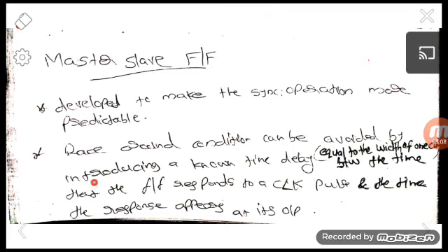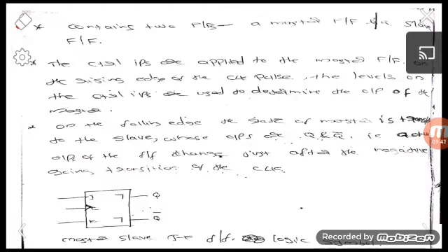Okay, so here we are introducing a time delay between the time that the flip flop responds to a clock pulse and the time the response appears at its output. That is, the response appears at its output based on the propagation delay of the gates.